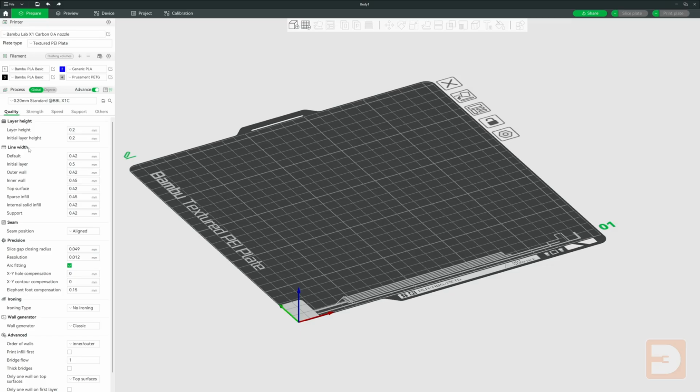This is referring to how wide the line is you're printing after it's been extruded. The filament will likely expand very slightly on the outside of the nozzle as it's pushed up against the filament that it was extruded just before it and has already started to cool. By default, for a 0.4mm nozzle, the line width is set to 0.42mm.